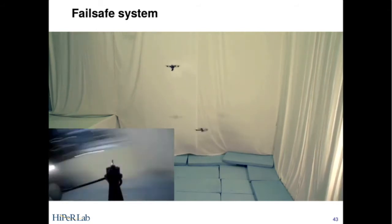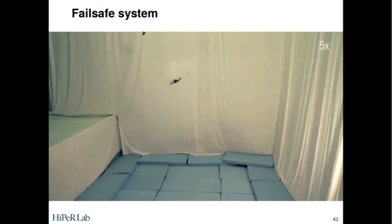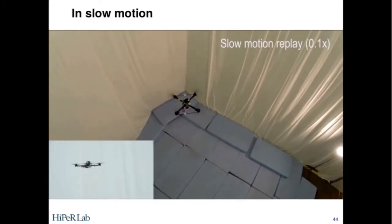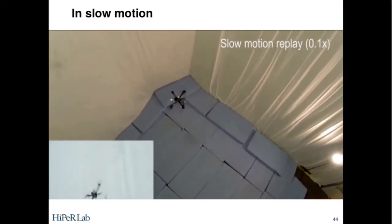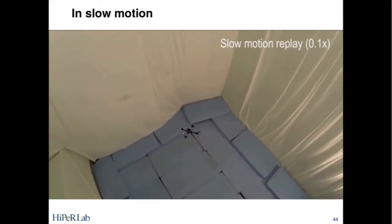Of course, initially, the vehicle is then suddenly missing one of these forces. So it sort of starts to tilt over. But then we can use this alternative control mode to fly the quadcopter back. So it's able to recover to its original position. And we can look at this again in slow motion. So this is the propeller that's going to fail. So we note initially the vehicle tilts over. But then it's able to use this alternative control strategy to recover to its original position.